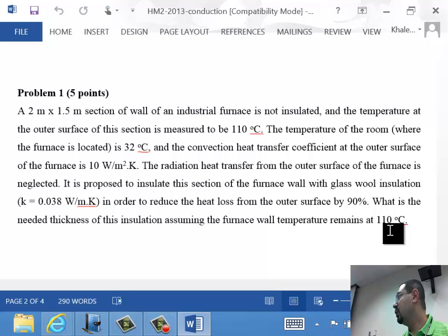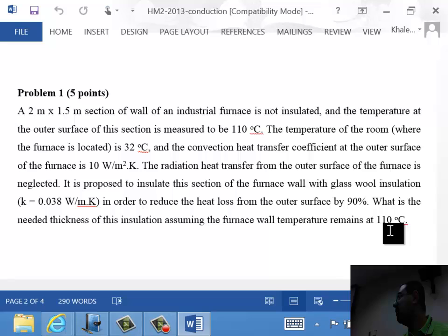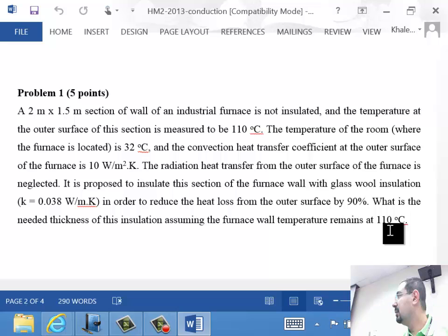So how can we reduce that heat transfer? He would like to reduce it by 90%. So the new Q is 10% of the old one. First you solve the old one and you figure out it's 100 watt. He doesn't actually want 100 watt. He's not happy. He would only like to keep 10 watts. So how much is the new wall? It's conduction plus convection next to each other. So Q is delta T divided by the two resistances added to each other. Does this make sense?